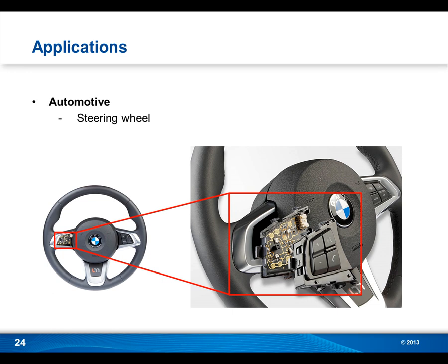And one thing I really like about this is this product started its life with the same housing you see there, with a PC board hot staked to that housing, and then the circuitry was on the PC board. And in this case, not wanting to take a risk with changing the mold, they just simply recast that housing in an LDS grade plastic. Then they were able to take the PC board out of the equation and put the circuitry directly on the back of the housing. So you're removing that whole other assembly from the manufacturing process.